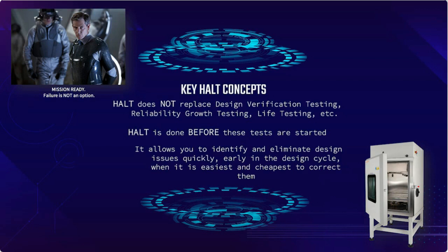Might make your reliability growth testing take an extra 2 or 3 or 4 weeks. If you can eliminate those failure modes and get into those validation tests and fly through those validation tests, now you've really gotten some value from the HALT. Not only do you have a more reliable product, but you're releasing that product faster. It's getting through the whole design validation process more quickly. HALT is your chance to identify and eliminate design issues early and fast, so you can fix them when they're cheap and easy to fix.